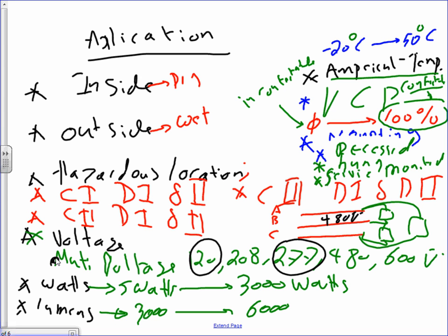So they're burning at 480. Or I can bring 120. In this case, the way I'm showing it here, this is how you wire with 480. Two phases going to the fixture, right? Typically, you don't do this indoor, outdoor, parking lot common. Okay, so we talked about this one.